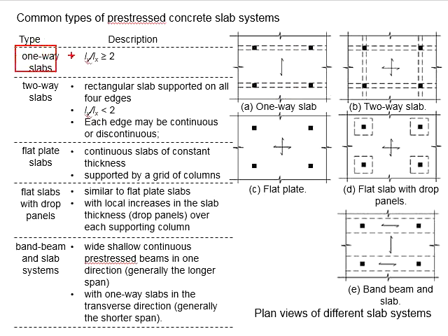The two-way slab normally refers to the rectangular slab, where its 4 edges are supported. There will be a grid of the beams at all 4 sides of the slab, and the Ly per Lx ratio is less than 2.0.